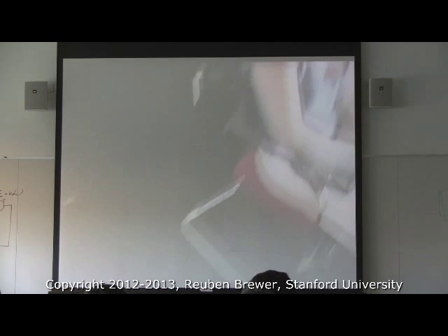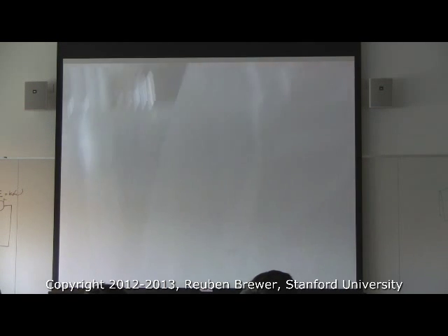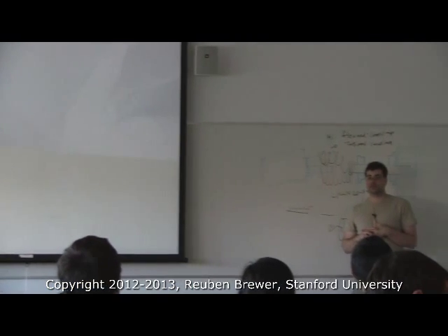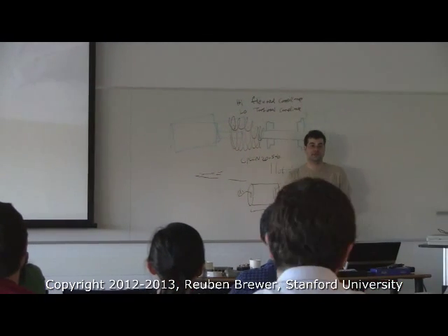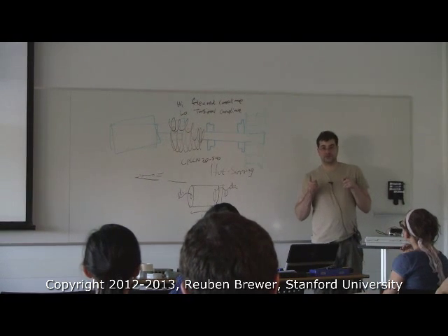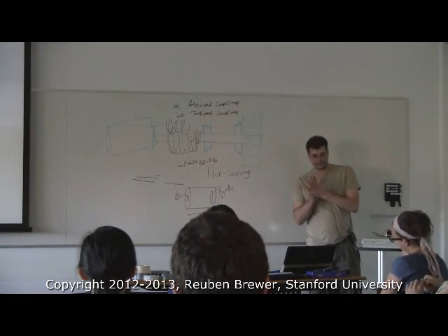Now, some of you who've done 218 will have used ones that have interlocking fingers. I hate those. Don't use those for precision robotics. They suck. Please don't use them. There's no reason. Just use the helical shaft couplers. Like spider couplers. Those blow. Don't use those.